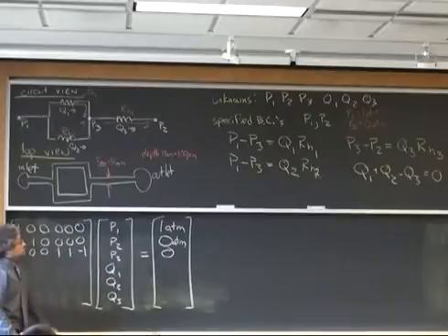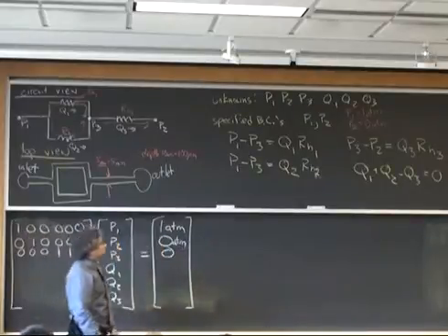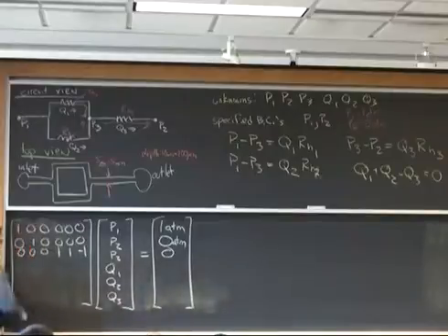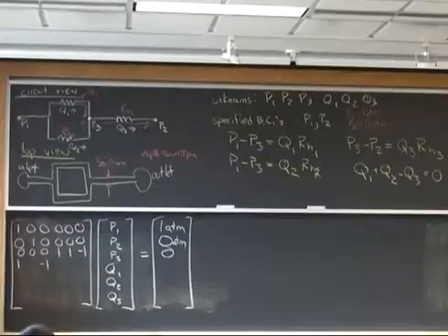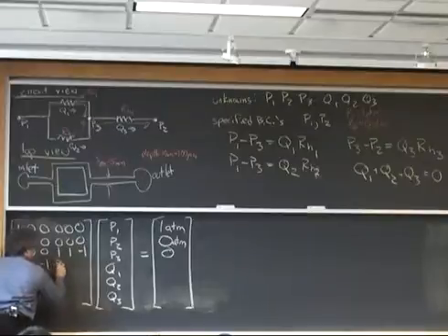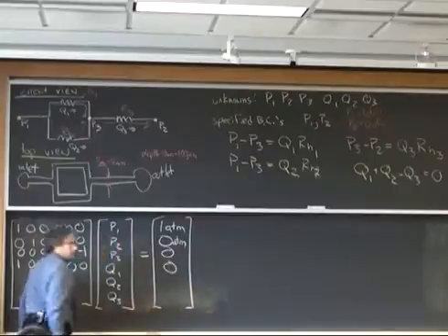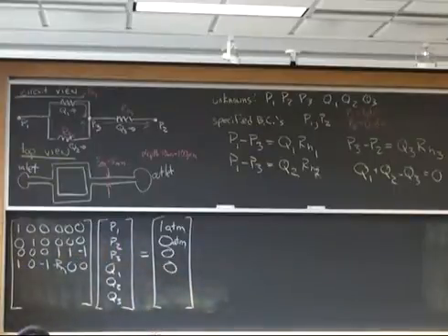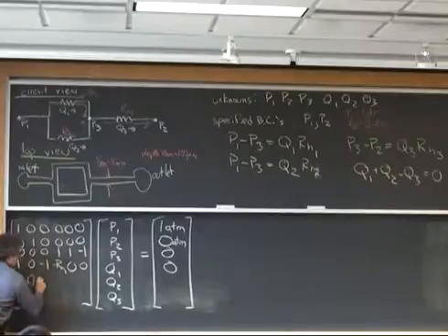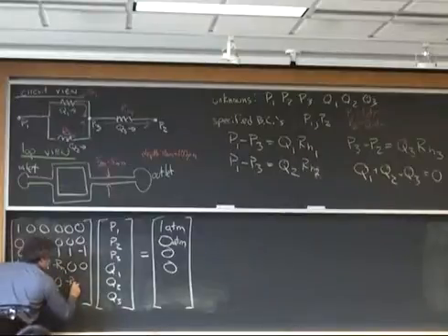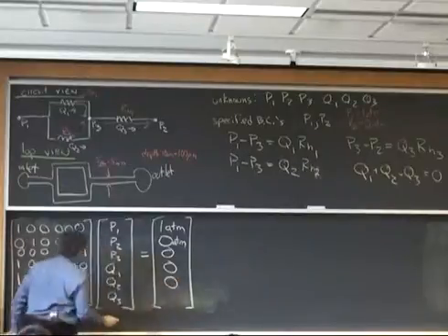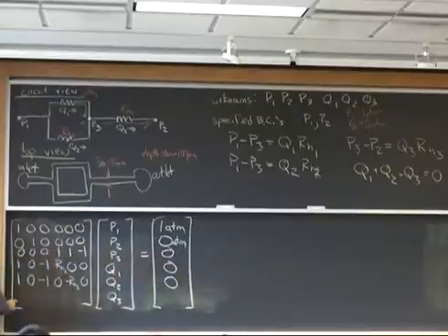And then I have 3 different equations which are in this Hagen-Poiseuille form. The first one, for example, is P1 minus P3 minus RH1 times Q1 equal to 0. And so on and so on.